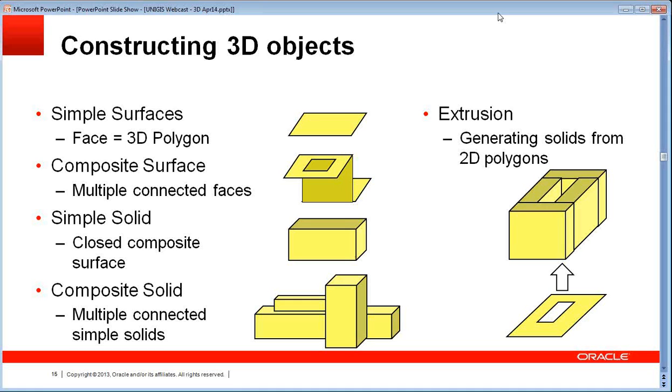Here are a couple of examples, and the most convenient way, particularly in city modeling, one of the most popular things I'm observing at the moment is what is illustrated on the right-hand side of this slide, namely they use the mechanism of extrusion starting from the building footprint, which they usually have from a cadastral map, in conjunction with an average height determined by laser scanning to at least determine a LOD1, a simplified block model of a building, to give you a bit of an idea of what the environment looks like in 3D.